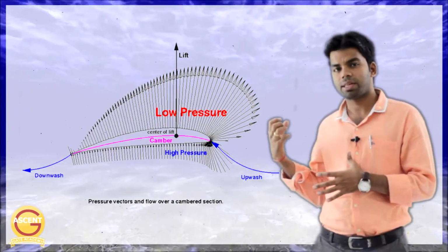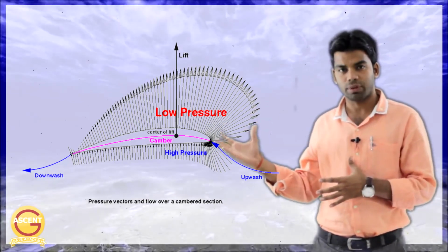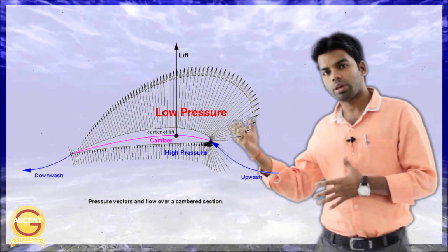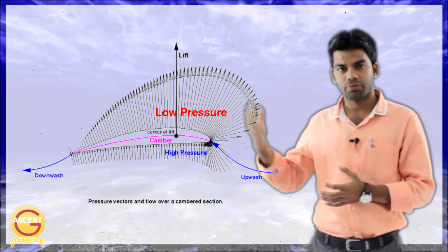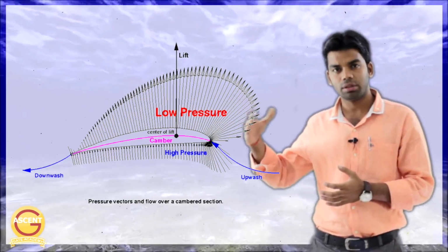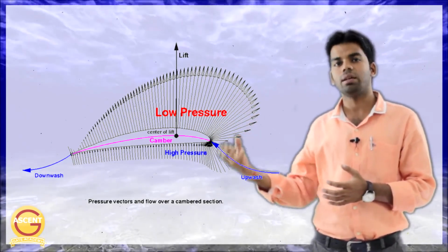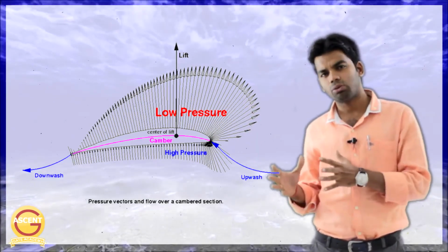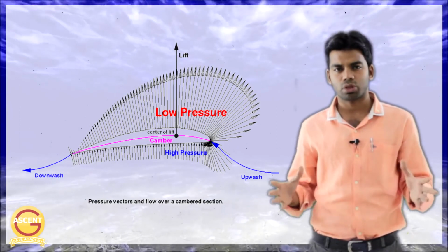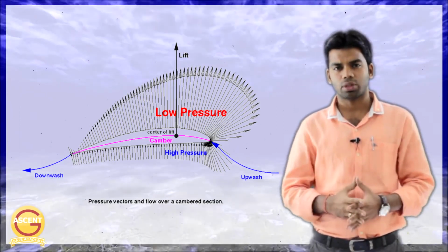Now what is the reason for the lift force here? When the airplane flies, above the airfoil there will be a negative pressure field, as you can see here, and below the airfoil there will be a positive pressure field. Because of this difference in pressure, the airplane will experience a lift force and it will fly. So these are all about airfoil. We are not getting into much detail here because not many questions were asked from this. We will just solve one or two questions from here.